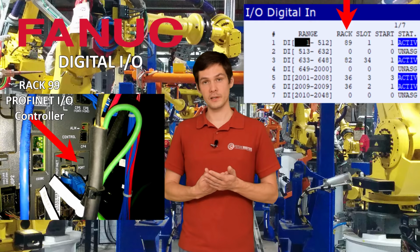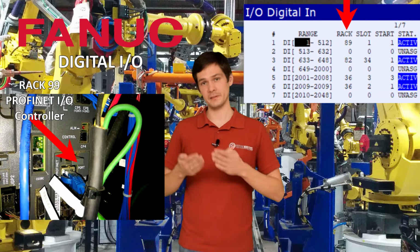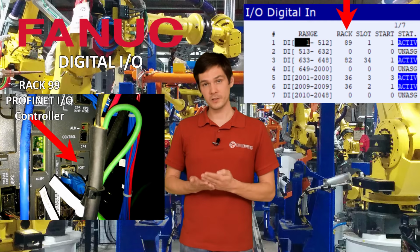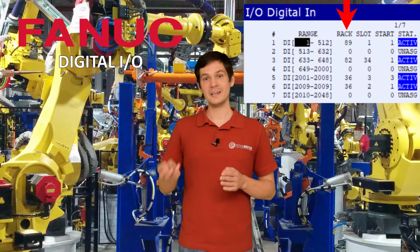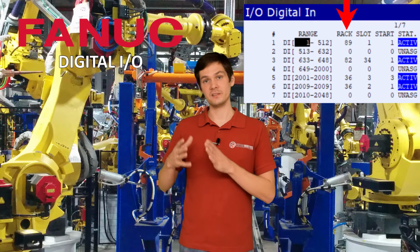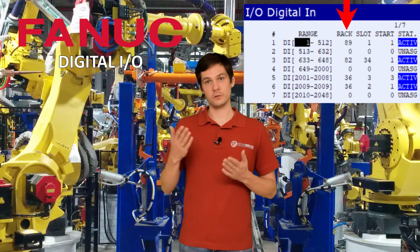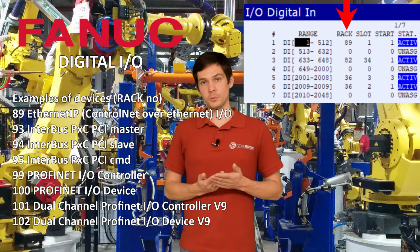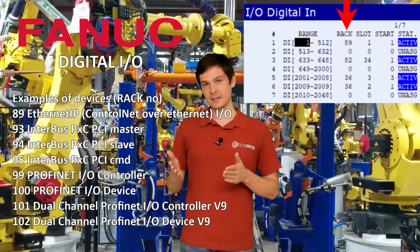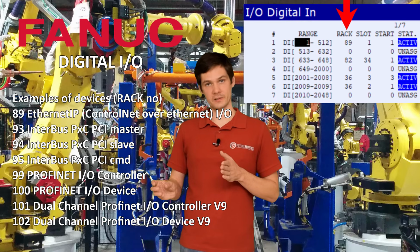In our case, we're going to talk about the communication with the PLC. Depending on the protocol that you're using, you're going to put a value in there, but basically those values represent the hardware that you're using. For example, if you're going to use the Ethernet IP protocol, you're going to put 89 in there, because 89 tells the robot, hey, now you're going to connect to the Ethernet IP card.